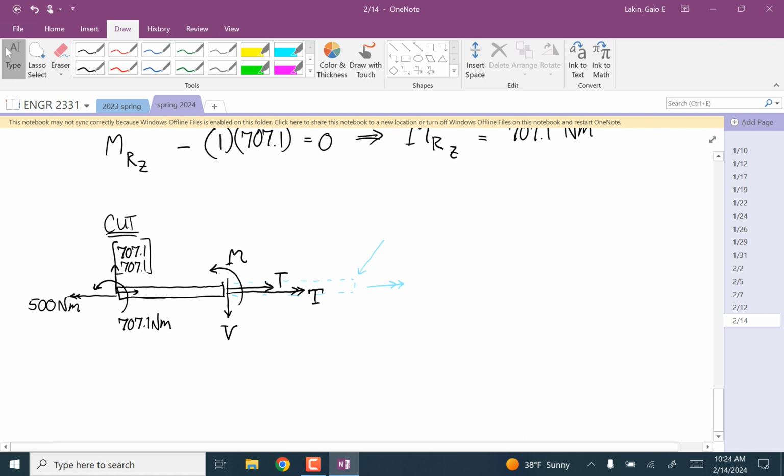The reason we didn't just keep the same sign convention is if we just called this a reaction, an R vector or something, then we'd calculate one thing if we isolated this side, and the opposite if we isolated this side. And it's confusing if you have it that way. What we want is a single set of internal loads that gives us the same answer whether we isolate this or isolate this. We want just a set of internal loads that tell us what this is, no matter how you calculate it. So we had to choose a new sign convention.